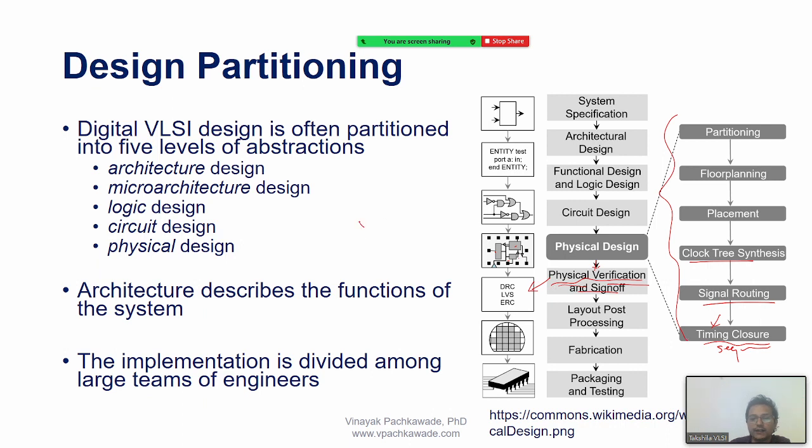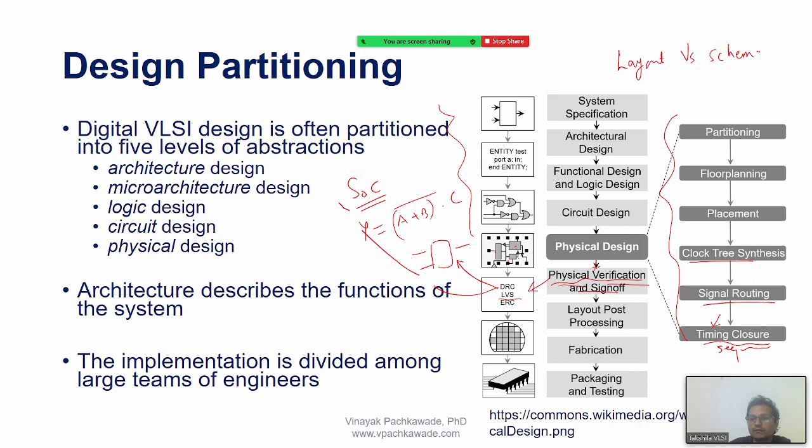I mean, you created this logic function. Okay, you got the inputs, you got the output, then you will run the DRC of this block. This is an example, but in actual practice you are running a DRC of the system on chip after doing all these procedures. Then you do LVS. What is LVS? They will ask you this question. Layout versus schematic.